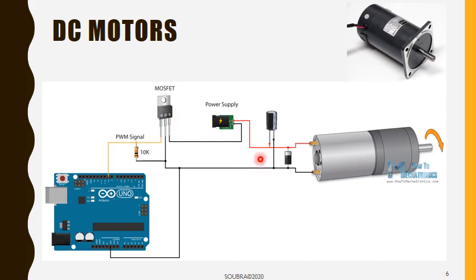But before tackling it, you can identify here a resistor. This is for safety; it is a pull-down, connected to the ground. And you can notice a capacitor here. The reason for having a capacitor is that supposedly we'll be having different voltages for different speeds. So in order to have some kind of cushion, it charges, then it discharges, so the changes will not be abrupt.